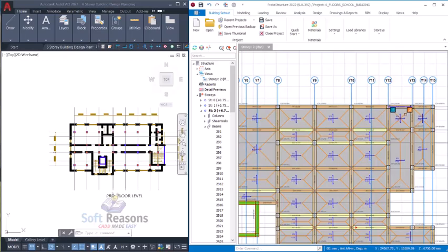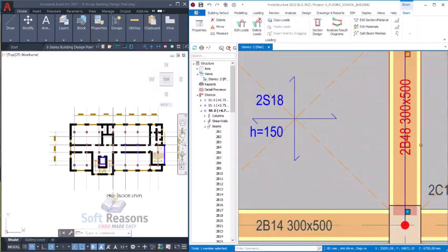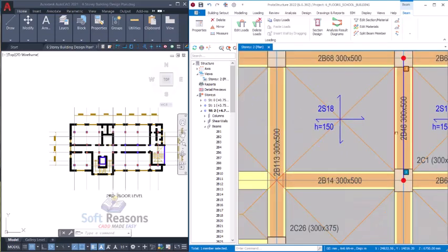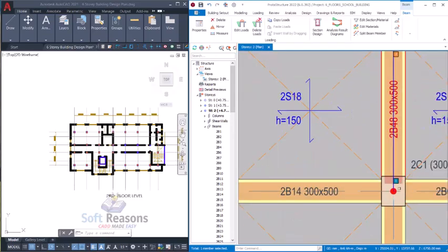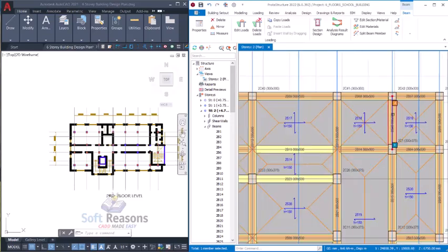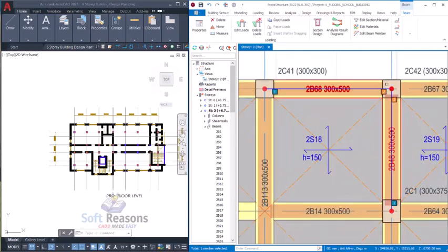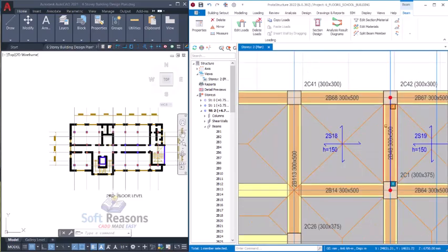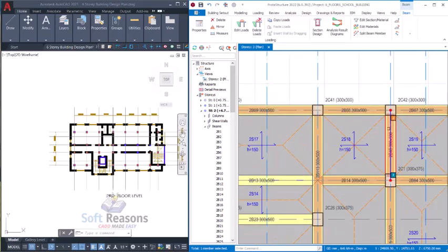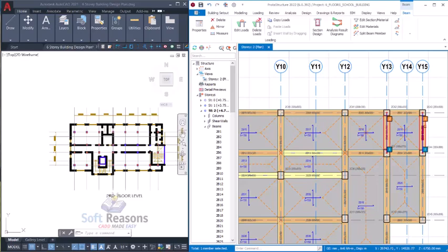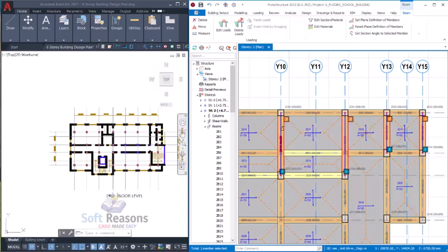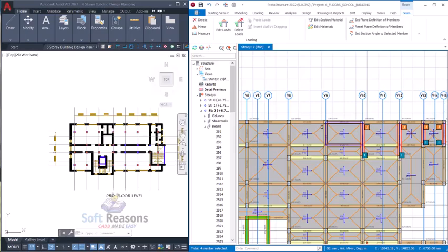For instance, you see this beam. This is second floor beam 48. So you see, going upward is discontinuous, so you have to anchor it to the column. Going downward is continuous, so there's no problem. But inasmuch as going upward is discontinuous, you fix it to the column successfully so as to reduce movement. So we select one, hold the control key, and select multiple of these, just like this.